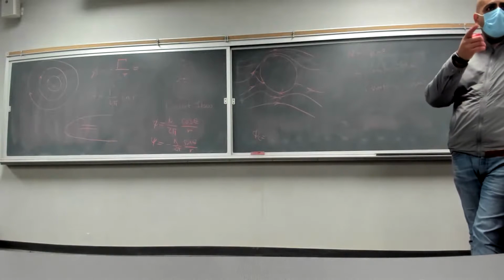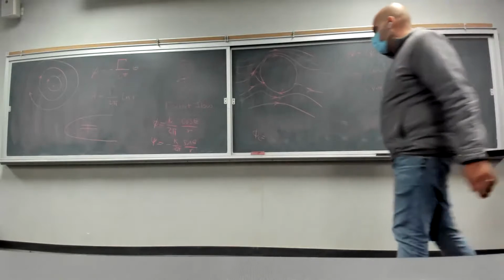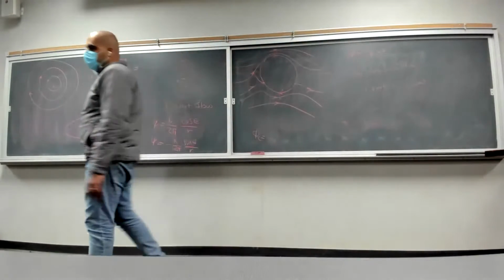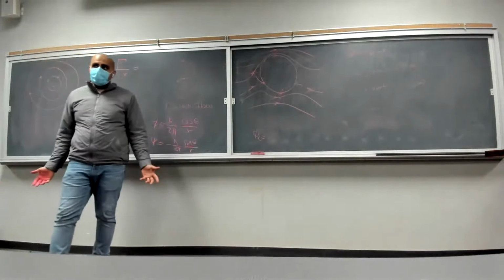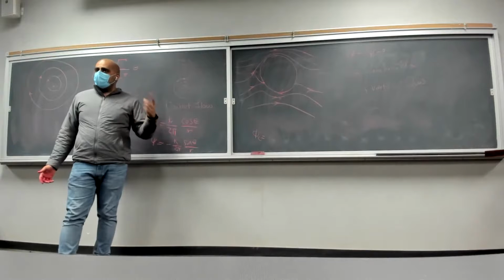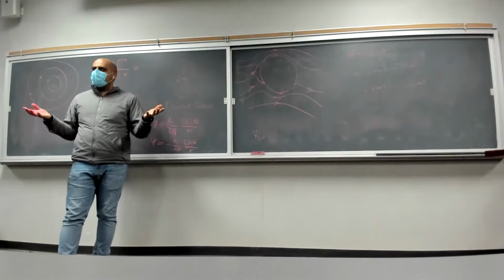So what Paul is saying, if you didn't hear him, or if you don't understand, is that if we are assuming friction doesn't exist, it doesn't really matter whether the cylinder is rotating or not, right? There is no way a rotating cylinder can tell the flow that it is rotating if friction is not there, right?